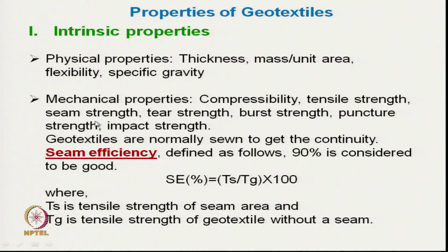We can calculate seam efficiency by knowing the tensile strength at the seam area and the tensile strength of geotextile without seam.